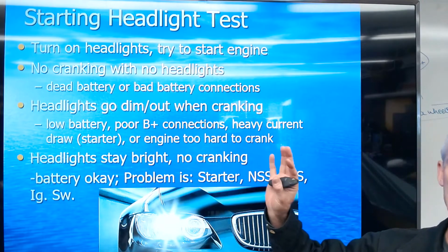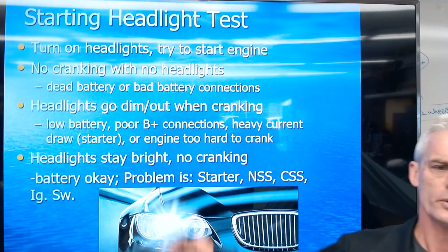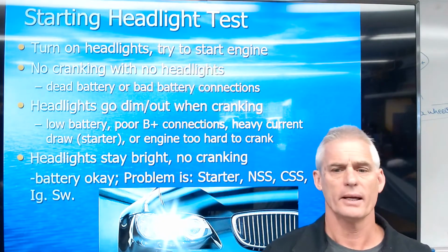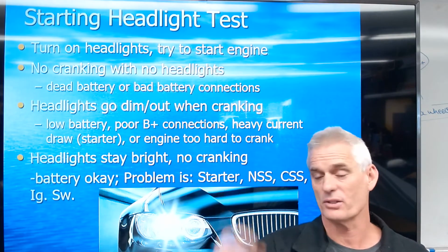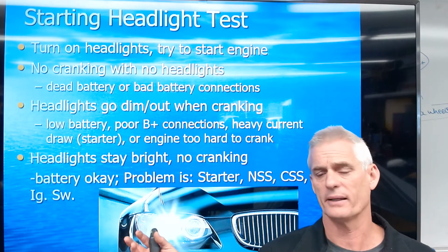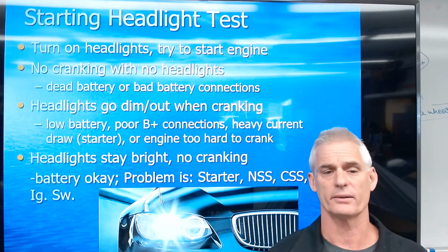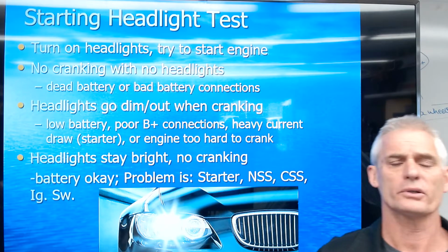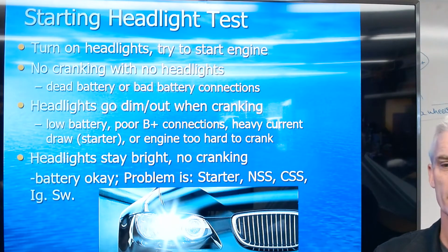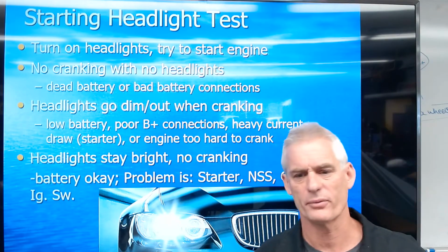But the reason why I like this headlight test is you can turn on the headlights, and if they don't come on and the dash lights don't come on, you know the battery's dead. It's completely dead or completely disconnected. But if you turn the headlights on and they're on, then you've got probably one of three scenarios.